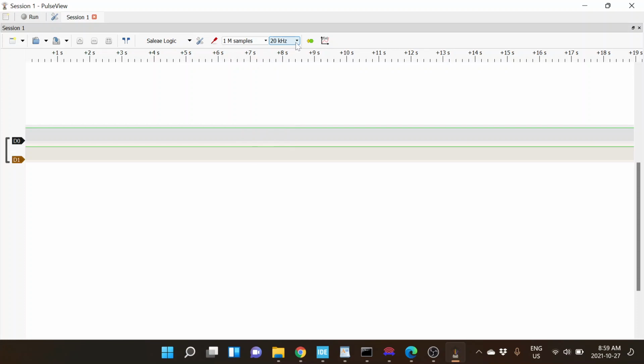Okay, 1 mega samples, and I'm going to say, hey, let's go up. I'm set for 115,200 baud, which is a kind of nice figure to stick around. I think a lot of the Arduino stuff is 9600, which is exactly this, but I'm set for 115.2, and I'll just have a couple of million samples. We'll just do 2 million samples. Okay, and then so let's try and run it again and see what we get.